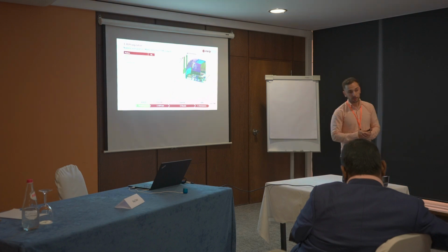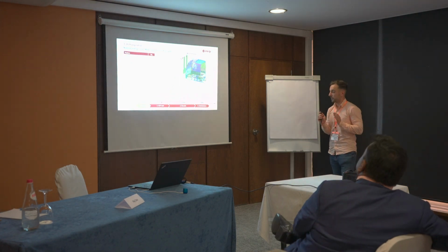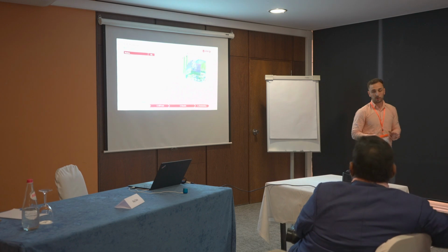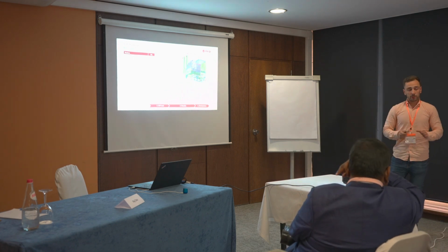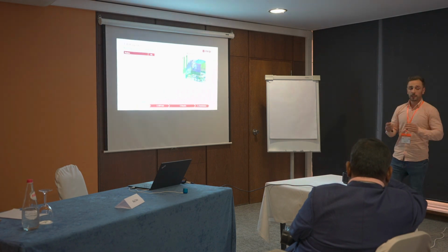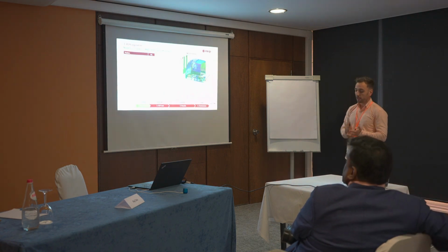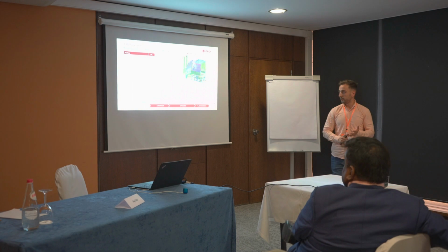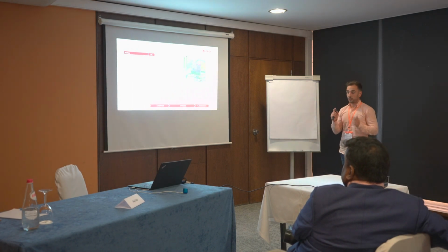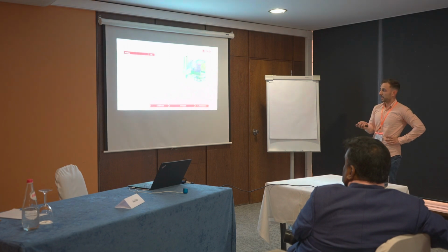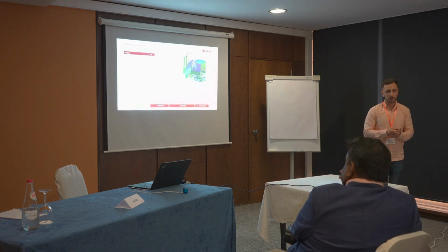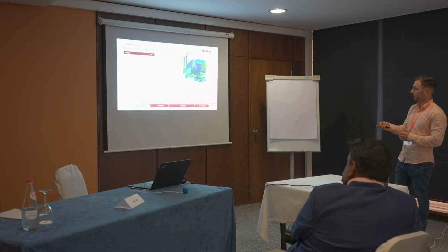Regarding the numerical procedure, like I said, it was performed in Pam-Crash. A lot of formulations are employed since we have different types of elements, types of materials, a lot of parts. The simulation is dynamic explicit with mass scaling. Regarding the materials, I have a quick summary.